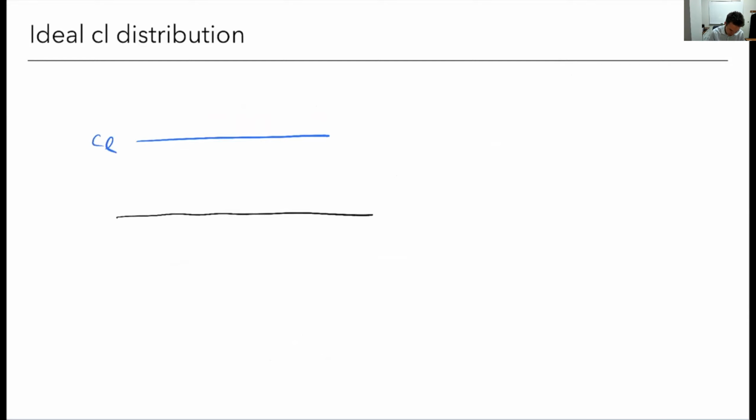We want a CL that's going to be just constant, so that when we hit CL max, every section stalls basically at the same time. This is close to what we generally want. The problem with this is tip stall is something that we're quite concerned about.